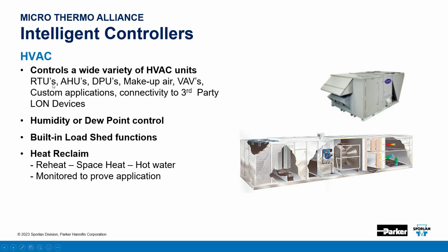So we can do rooftop units, air handling units, dual path units, makeup air, variable air, custom applications, and connectivity to third-party LON devices. We can control based on humidity or dew point. We have built-in load shed for the areas of the country where load shedding is a prerequisite.